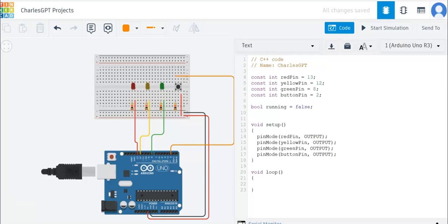Since I want to be printing something in the serial monitor, I'll just use Serial. So to print something in the serial monitor, you do Serial.begin(9600). So this is what you use to print something in the serial monitor. Then what did I want to print at first when we start the program? Let me just put this as the first thing we are going to print.